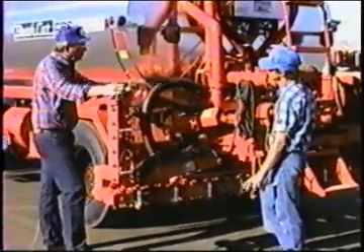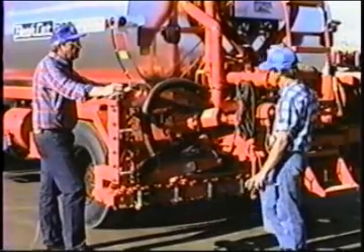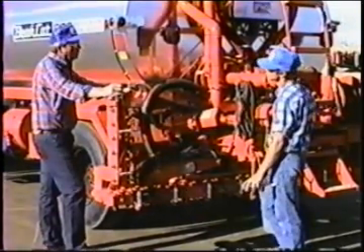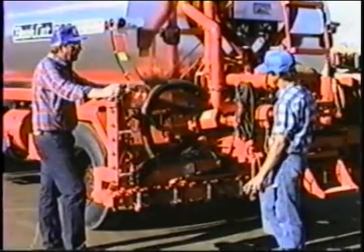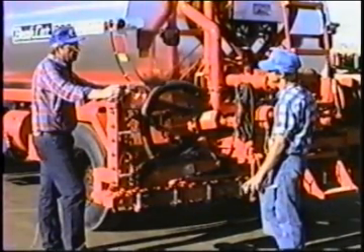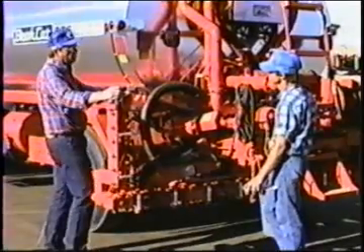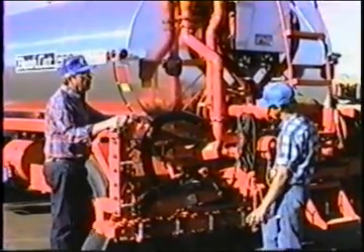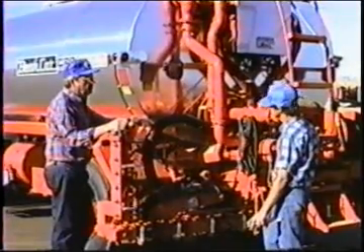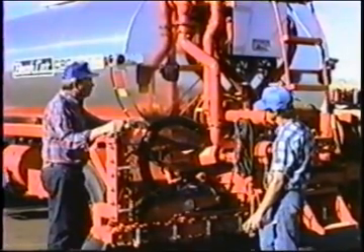And on the computer trucks, if that spacing is somewhere around 10 to 15 thousandths of an inch, that's just fine. Good rule of thumb, if you need to check that, you can just screw it in to where it touches the gear tooth and then back it out a quarter to a half a turn, and that'll set the spacing just right.